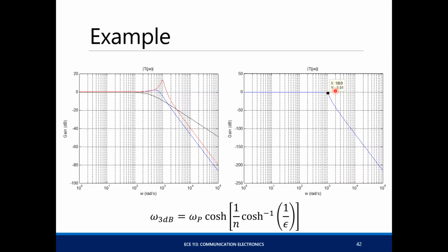So to add things all up, this is your first order filter, this is your second order biquad, and this is your other second order biquad. This is the first circuit I've shown you, this is the second, and this is the third. And if you look at the transfer function of the total, you multiply all these, you get this response for your Chebyshev filter.